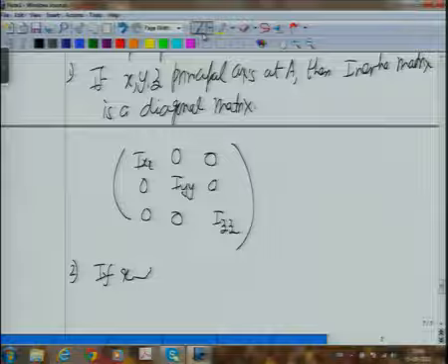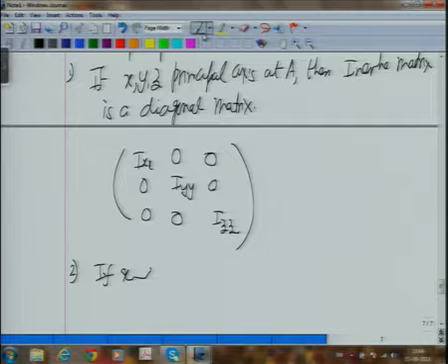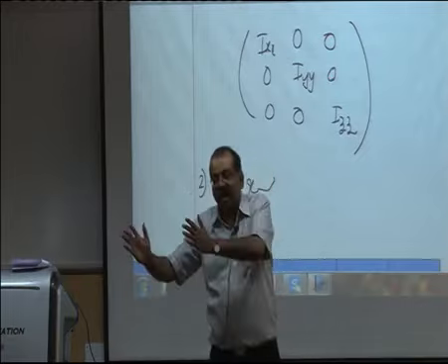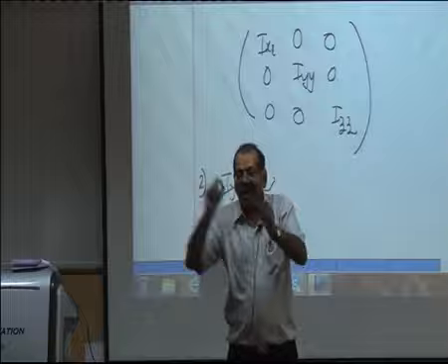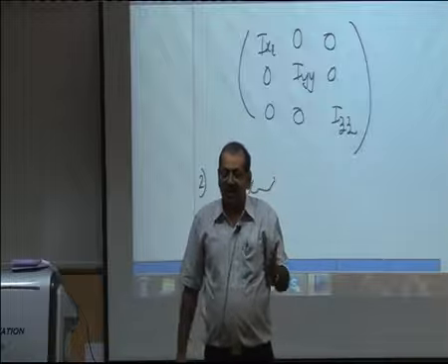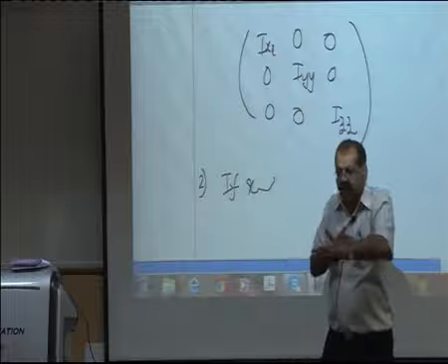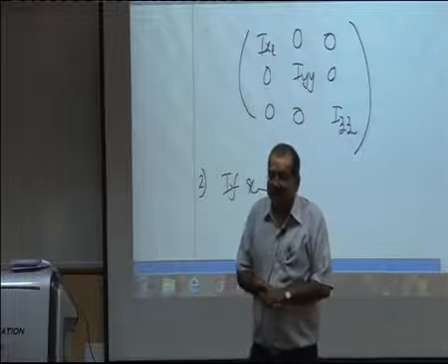If the axis is passing through the middle, the left part and right part will give equal and opposite contributions. For each x, yl and yr will cancel out. Therefore, whenever there is a plane of symmetry in the body, perpendicular to that is a principal axis.